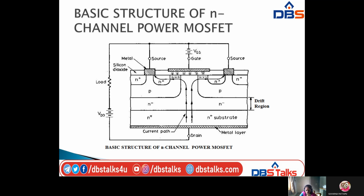So this is the drift region. Here in N channel MOSFET we have N plus plus, N plus plus and N plus plus, and after that P and N minus, and this is N plus and this is N plus. This is the current path, when you are draining the MOSFET. So this is the basic structure of power MOSFET. And here we connect the load between the drain and source.